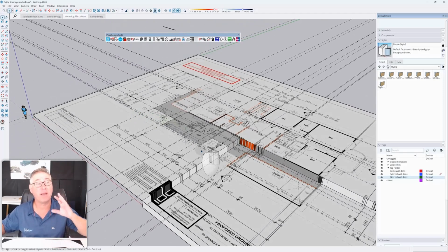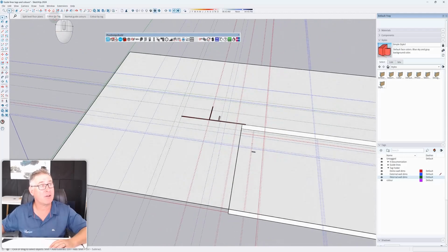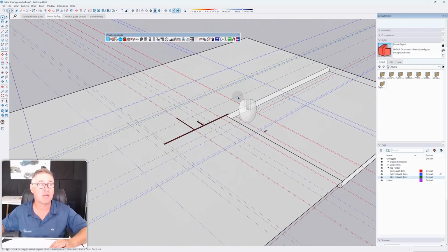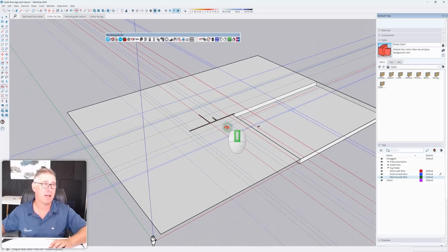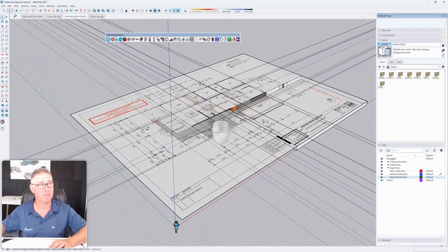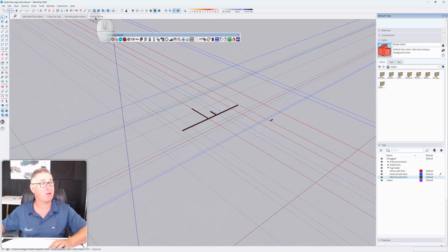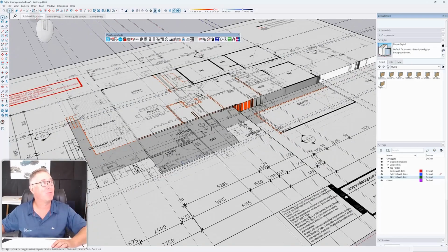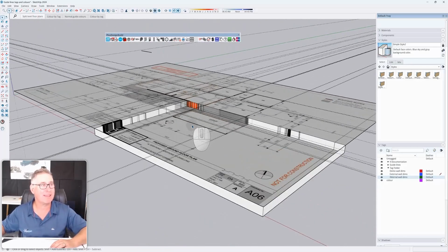I'll quickly go through it, but today what I'm going to do is show you how to color those guidelines, so that you can just go, well, external walls are blue, demolished walls are red, and new walls are green. This will be more for renovation, remodel type people. I'm also going to show you how to turn that on and off, and I'm also going to show you, instead of using guides, in some cases it's easier to do rectangles because, you know what, it's just easier. Right, I'm also going to talk about split level floors, and we might get into that first.